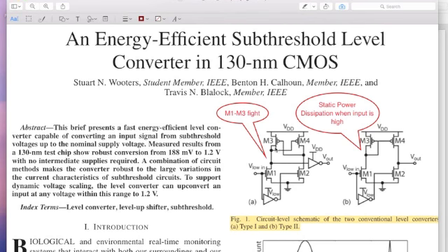But before getting into that, let us look at the problem which we have. Why do we need something different from this standard thing which we saw? The reason is that when you look at the condition when M3 is on, that means this node here is high, and you want to bring this node down. When input V low goes high, M1 turns on and is supposed to bring this node down, right?